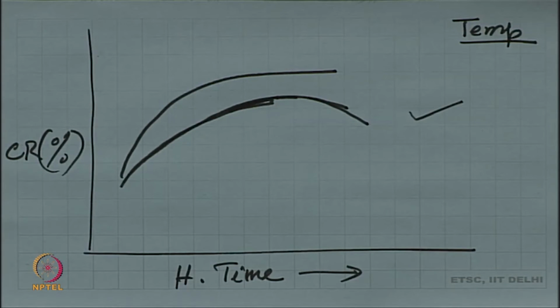So, have you ever kept any material which is called a polymer fiber in an oven for a longer period of time? Have you ever seen what would happen? You never got a chance to keep any material in an oven or a hot environment for a long period of time? If you see, it becomes yellow, starts becoming yellow. If any material which was approximately white starts turning towards yellow, you can appreciate that there is some degradation starting. Something which was white is becoming yellowish. That means certain types of groups which can absorb something from the visible radiation have started growing, and you start looking at something which is different.